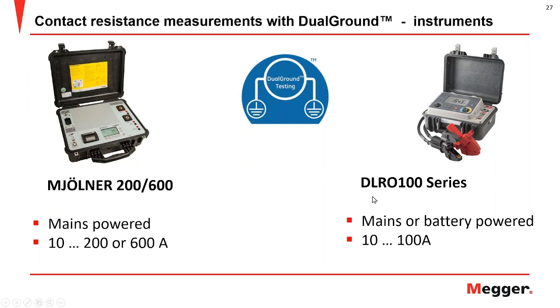The DLRO 100 can perform from one battery charge two separate tests of 10 minutes each at the maximum output current of 100 amps, and the Mi, being mains powered, has a continuous duty cycle: 200 amps continuous for the Mi 200 and up to 300 amps continuous for the Mi 600.